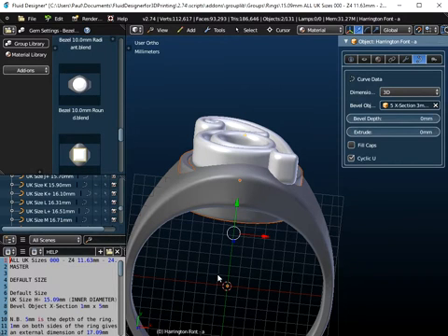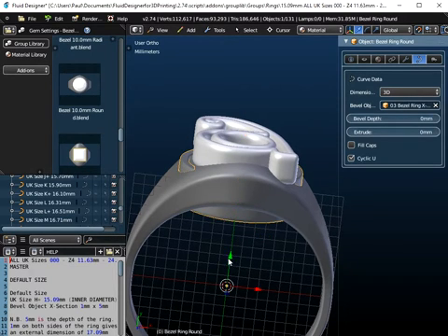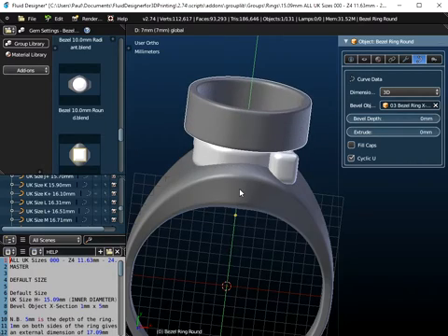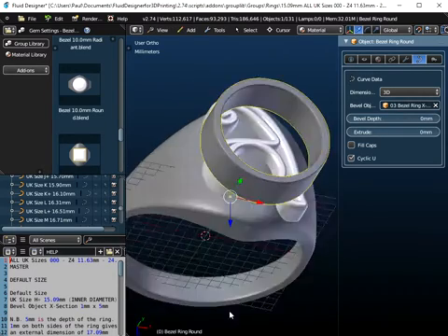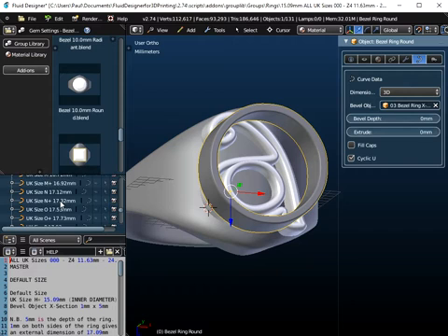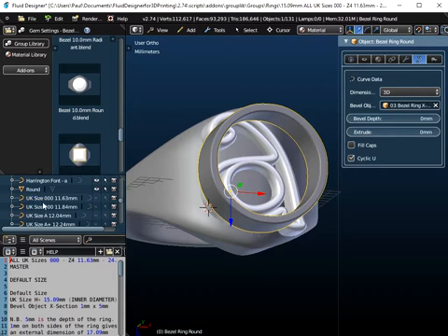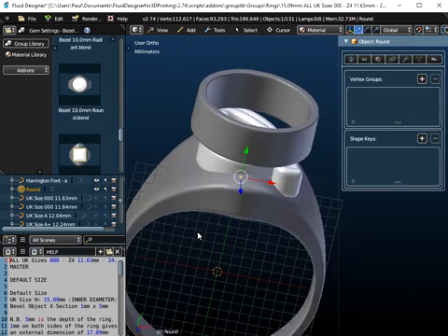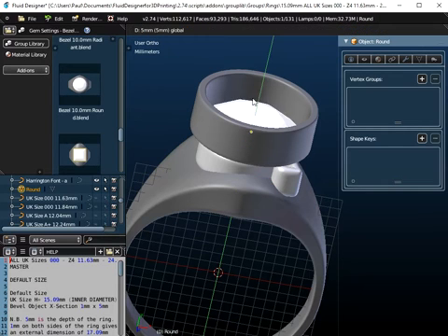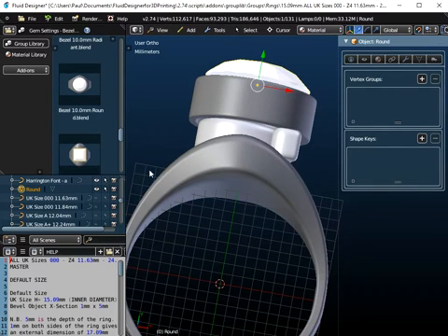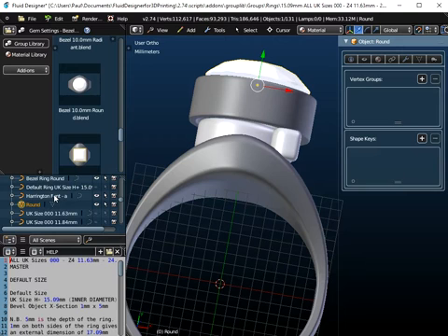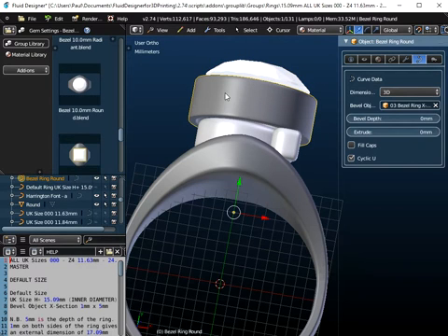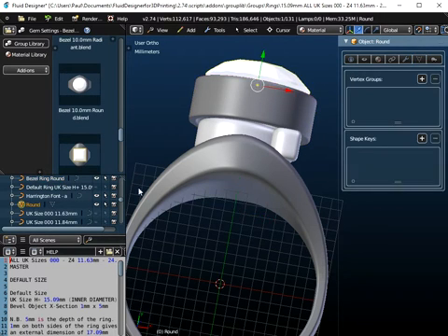that's brought them in. What we need to do now is to reposition them, and we need to resize them. Okay, now I can't quite see the gem at the moment. It was the round gem, so if I just look for R for round in the outliner panel here, that should select the gem. So if we just move the gem up, there you can see the gem. So we've got a bezel ring round, which is this object, and we've got the round gem.